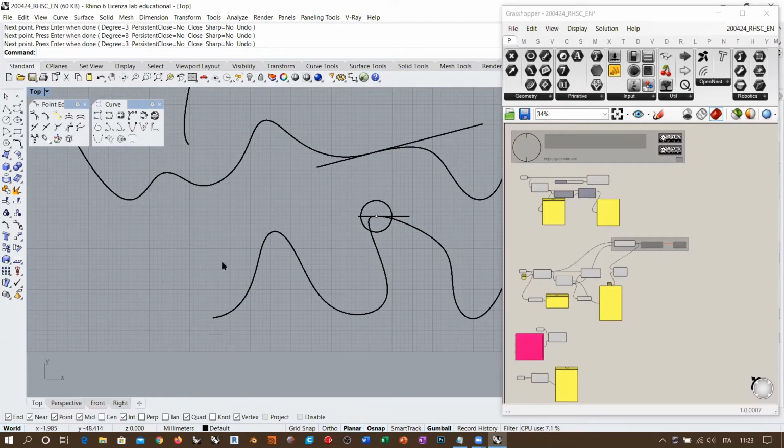All in one single line, not like drawing a NURBS curve and then drawing a straight line with a polyline and then another NURBS curve segment and then joining all together. I want to do this all with one single NURBS curve command execution.